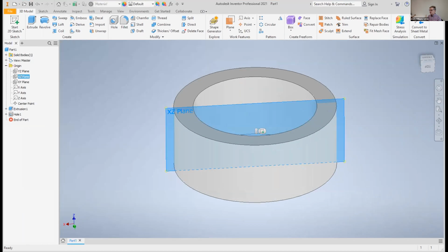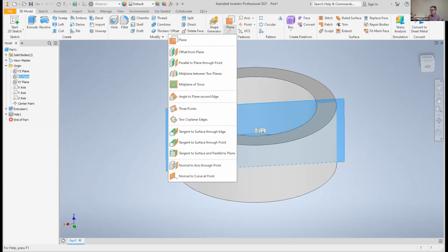I have a religion whereby whenever I add a feature to something, I start off in its own plane. It gives it a place to be. It gives me a place to go and say, hey, I need to work on that thing in that plane. We're going to add text to this. Text, at least for starters, before we extrude it or emboss it, is just a 2-dimensional thing. The ring is already 3-dimensional, so we need to introduce a plane to put our 2-dimensional text in, okay? So get in the habit of doing this. I start off with a plane, and I'm really big on making offsets. So I make an offset plane.